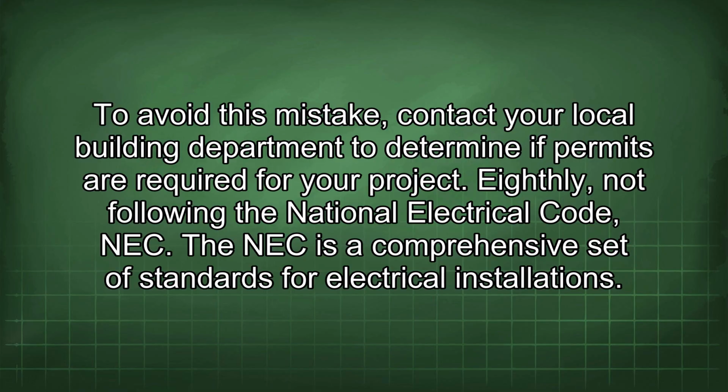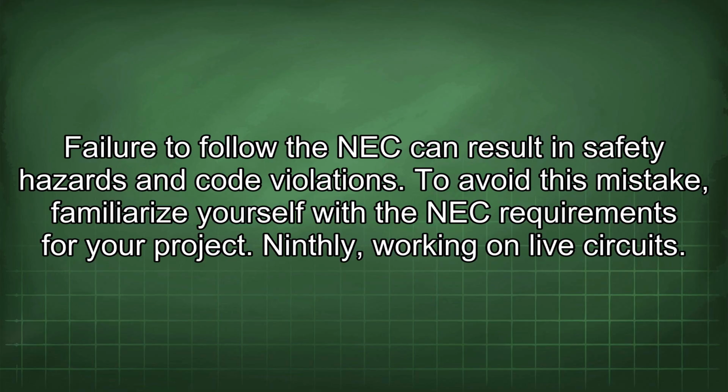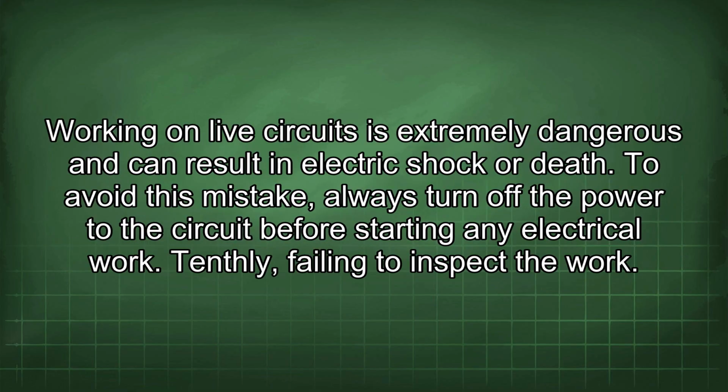Eighthly, not following the National Electrical Code, NEC. The NEC is a comprehensive set of standards for electrical installations. Failure to follow the NEC can result in safety hazards and code violations. To avoid this mistake, familiarize yourself with the NEC requirements for your project. Ninthly, working on live circuits. Working on live circuits is extremely dangerous and can result in electric shock or death. To avoid this mistake, always turn off the power to the circuit before starting any electrical work.